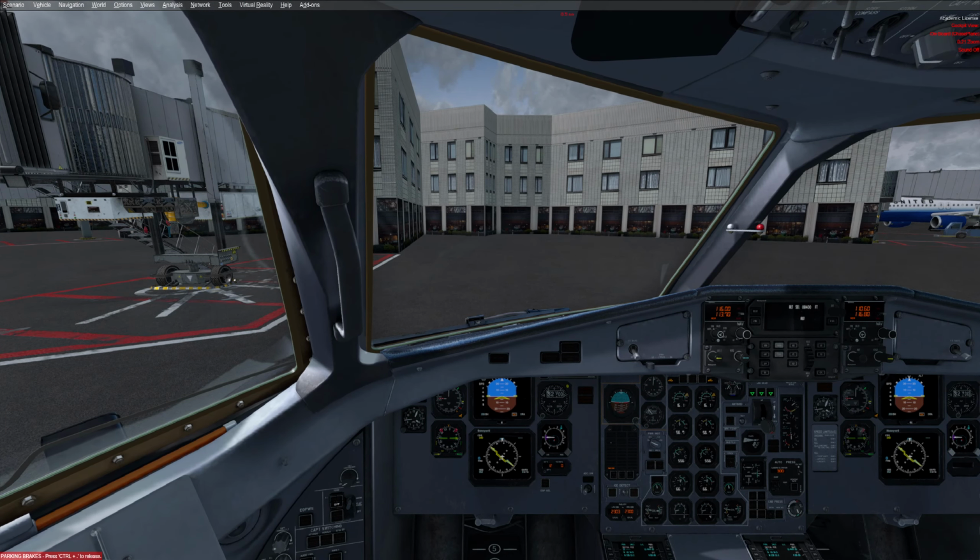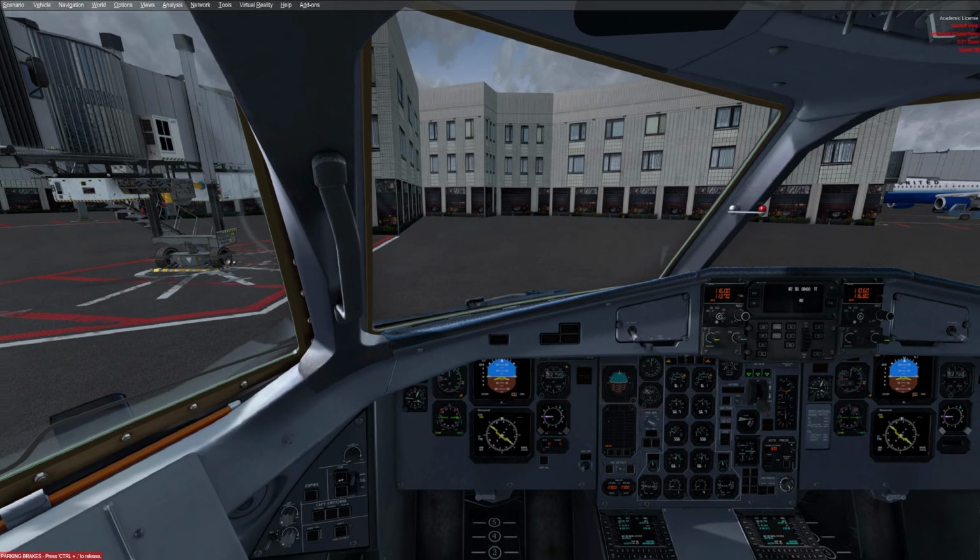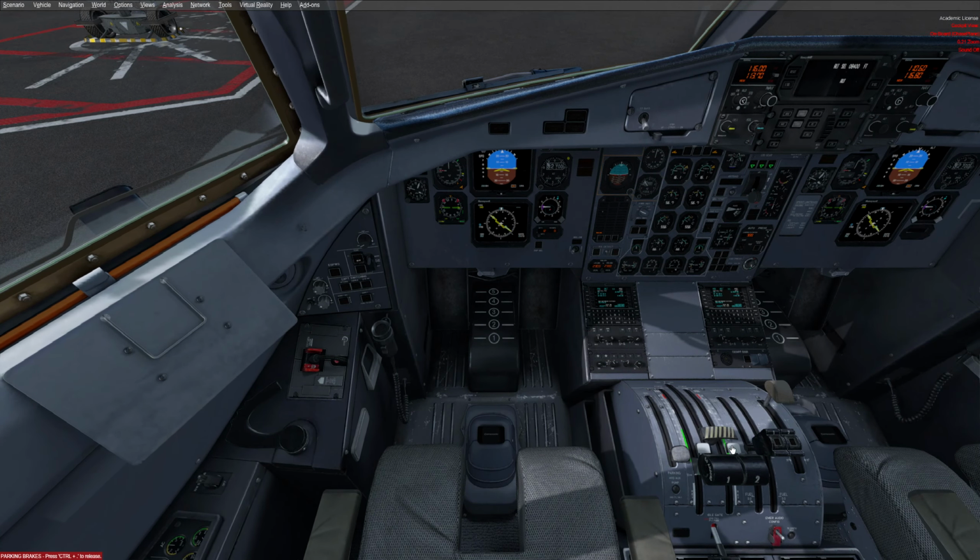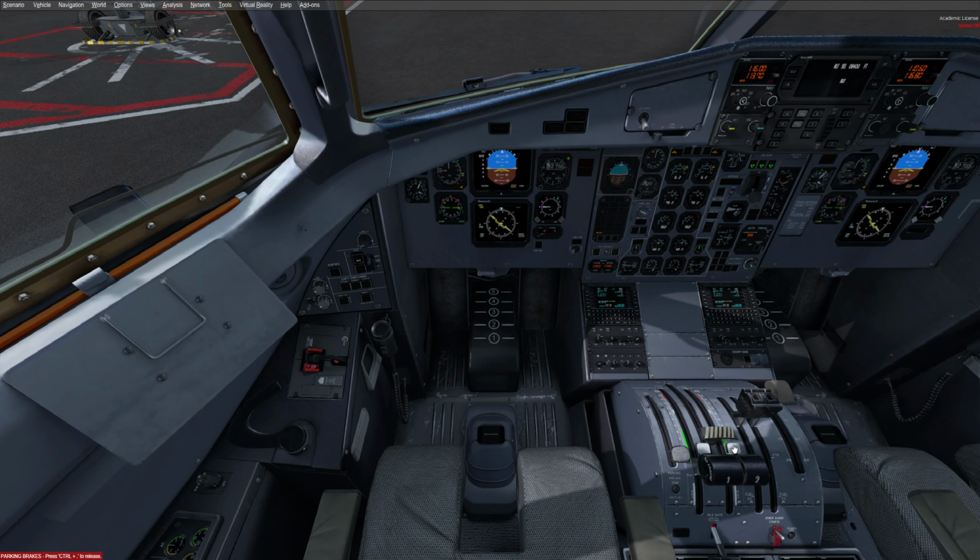Okay. Now, the control levers, if we've been pushed back and we're ready to go, we're going to left click on both of those up to the auto line, and we're going to leave those alone. Now, this is how we're going to taxi. We got takeoff here, ground idle there, auto there. There shouldn't be anything that's really needed now in order to taxi. We may just give it a little bit of thrust for the power levers there to get things rolling, but other than that, it should be good.